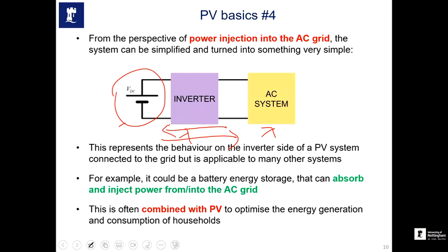Now, my question here, based on your knowledge about PV, do you think the PV panel can accept power? If there is only PV after, as I said, there could be a DC-DC converter in here, and there I have the PV. If I don't have anything else, that means from the AC, if the inverter is bidirectional, I'm trying to push power into PV.